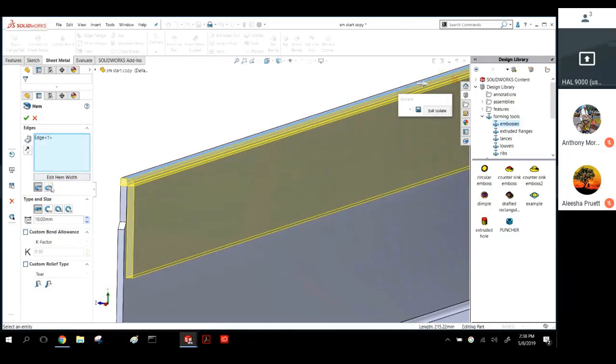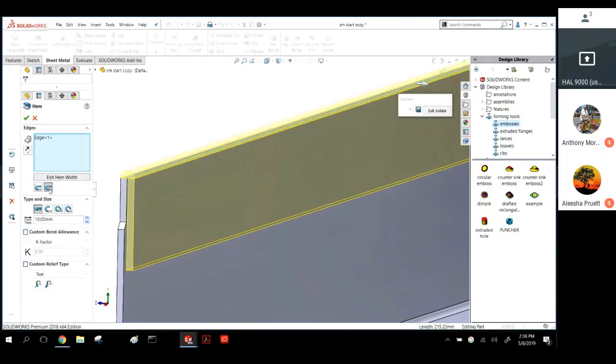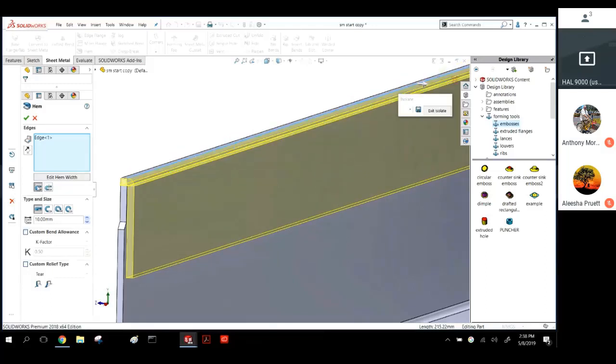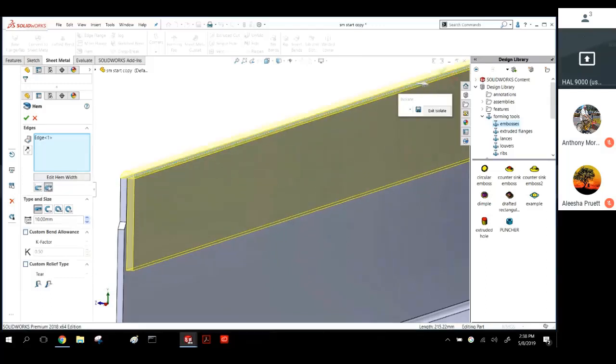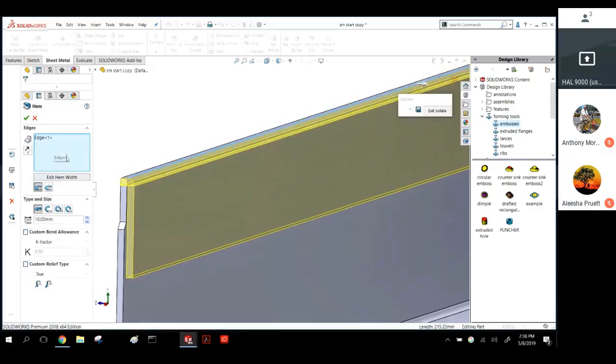So whether you're dimensioning, you want the round part to come up over the original top, or whether you want the original top to be where the top of the round is. That's what these two settings do for me. Also, this one is going to bend it back, theoretically back to the other piece of metal. It has a really small air gap of like 0.01. There always has to be a gap in there for SolidWorks to be able to unfold a piece of sheet metal. If it's got non-uniform thickness, it gets confused and won't do it. So it leaves a little gap.